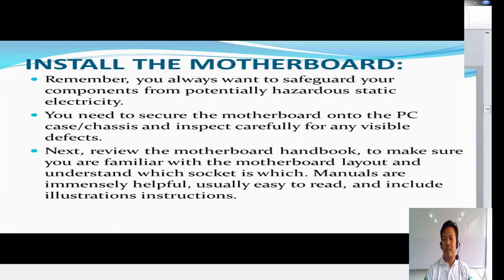So install the motherboard. Remember, you always want to safeguard your components from potentially hazardous static electricity. So you need to secure the motherboard onto the PC case chassis and inspect carefully for any visible defects. Okay. Next, review the motherboard handbook. Make sure you're familiar with the motherboard layout.